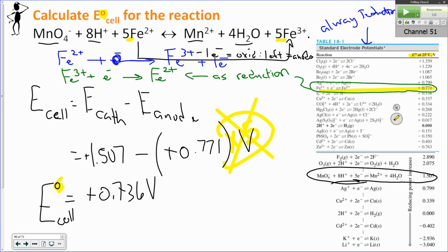And you have a couple of things that make it harder when it gets cold. One is that the lubricants in your motors start to thicken up. The viscosity gets higher, and it's harder to get the crankshaft to start coming over as it's going through this basically sludge initially. So how do they overcome this? Especially with diesel motors, because diesel motors use a higher viscosity oil than gasoline motors. So you know what you do? You turn the coils on. What do the coils do? Just heats it up. Yeah, an engine heater.